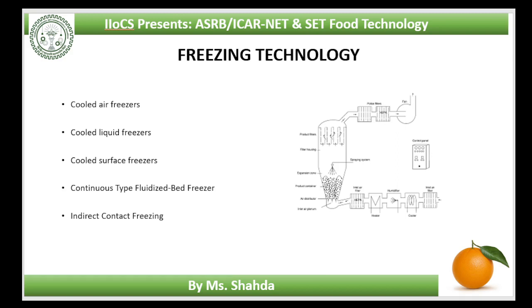Indirect contact freezing is based on the principle of placing the food on plates, trays, belts or cold walls so that it is in indirect contact with the cold wall. The food usually has flat packages, is placed between shelves, and there is provision after loading for applying pressure to squeeze the shelves into more intimate contact with the top and bottom of the packages for faster freezing. All is enclosed within an insulated cabinet.